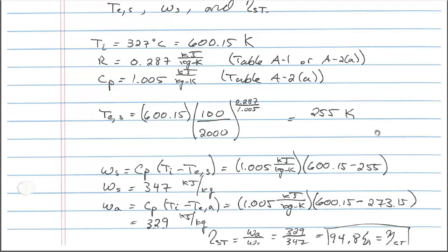And how engineers actually use this isentropic efficiency is by helping with diagnostics. So, for example, if you're operating a steam power plant, you're constantly measuring your inlet and exit temperatures and pressures. And since you're using steam, you can determine your inlet and exit enthalpy and entropy and do an isentropic efficiency analysis on that process.